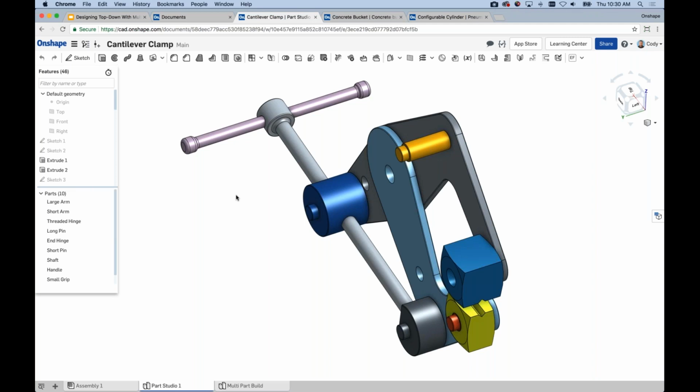But the question that often comes up in that kind of workflow is, you have a multi-body file. It generates a whole bunch of part files for each body, right? And then you add all of those part files into an assembly. Where do you go to make your change? Do you go back to the original multi-body file, make your change, and export all the parts out again? Do you open up and edit the intermediate part files that are generated as part of the process? And that question and all the kind of noise that's generated when you export all of those bodies as files and then insert them in assembly, it causes a lot of confusion, just a general kind of tedious workflow.